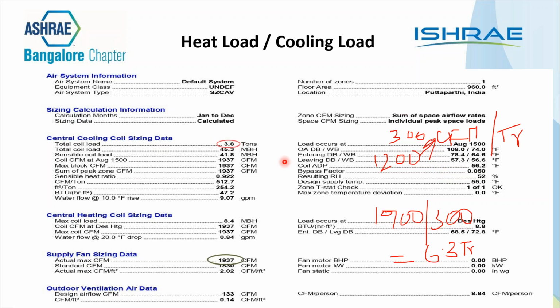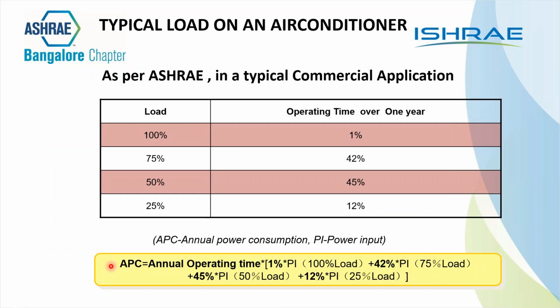So you get something called a refrigeration tonnage here, which is your cooling coil load, and then you need a quantity of air to keep you comfortable. That is known as the dehumidified CFM, and it is always important for us when we are talking about comfort air conditioning. The dehumidified CFM, or the quantity of air, is more important for us than the refrigeration load. However, we need to balance between the outdoor unit capacity and the indoor unit capacity, and that is what we generally try to do optimally in a VRF system.